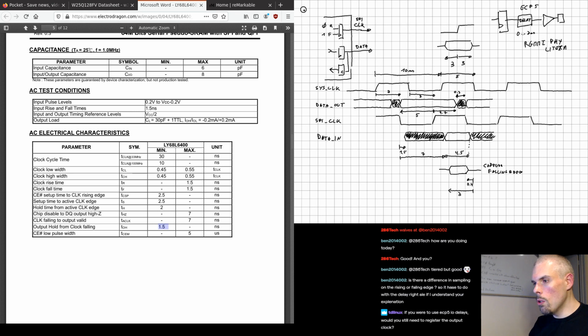Technically, you can input the clock and the open tools will let you do that, but because it's using random fabric resources to route that clock, the delay is basically random. You have no idea what it is. And so guaranteeing any kind of phase relationship between that and other things is impossible, and so Diamond just forbids it altogether. That's for input clocks.